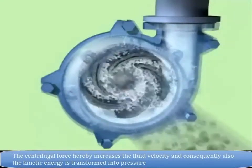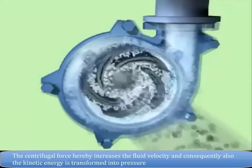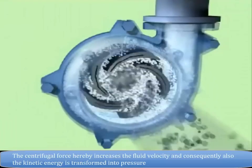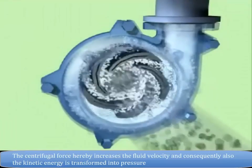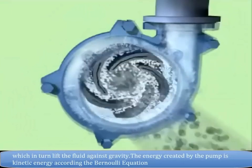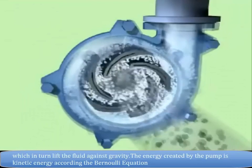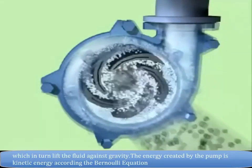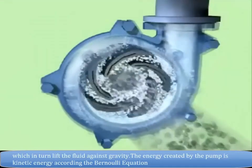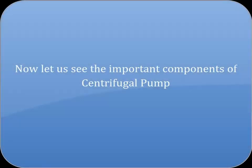The centrifugal force hereby increases the fluid velocity, and consequently the kinetic energy is transformed into pressure, which in turn lifts the fluid against gravity. The energy created by the pump is kinetic energy, according to Bernoulli's equation. Now let us see the important components of a centrifugal pump.